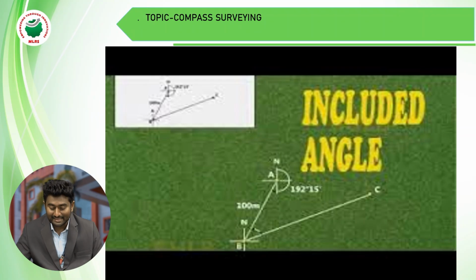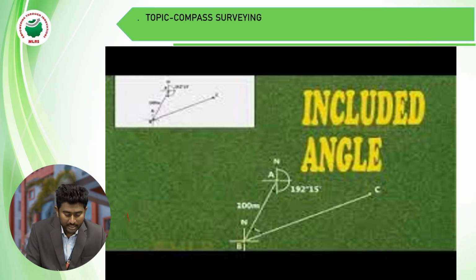Next, included angles. Included angles are measured with the compass. In compass surveying, the formula is: included angle equals back bearing of the traversing line minus forebearing of the traversing line.